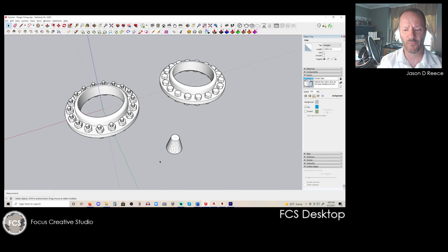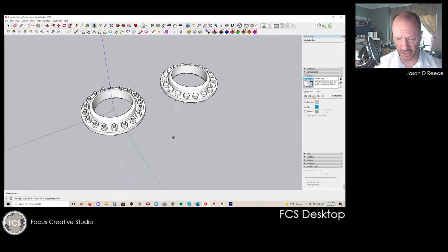Now this is really powerful when you start getting into rivets and you want to think about orientation of the build plate and the 3D printing of your models. Because we don't always need to do rivets and bolt details with a true 90-degree angle. Think about that relief angle. In some cases it works in your favor and actually allows adding more detail because it'll print more successfully. So we're going to go ahead and delete these and jump in here and get these started.